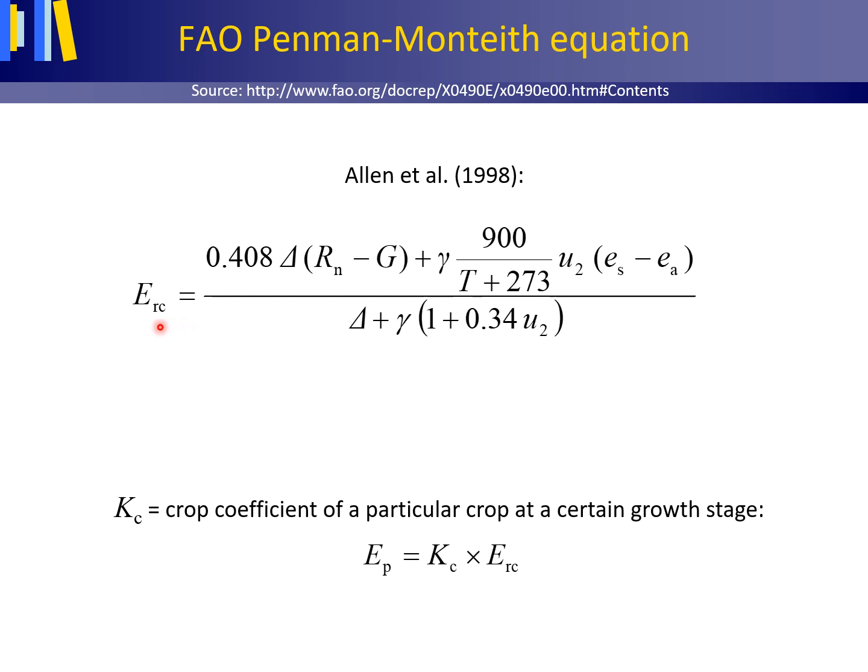This equation is the Penman-Monteith equation for a grass crop height of 0.12 meter, a standardized height for wind speed, temperature and humidity measurements at 2 meter above ground level, an albedo of 0.23, an aerodynamic resistance in seconds per meter of 208 divided by U2, where U2 is the wind speed in meters per second at 2 meter, and the surface resistance of 69 seconds per meter.